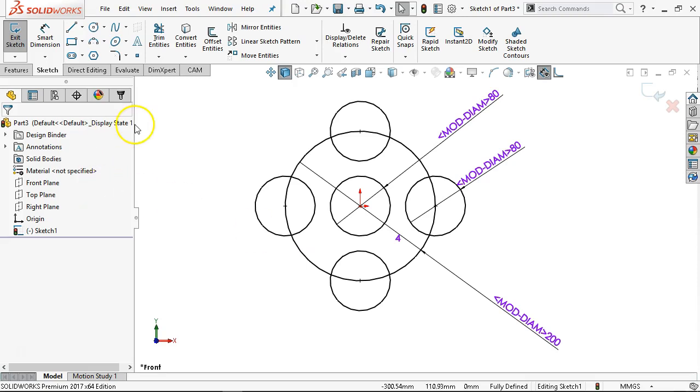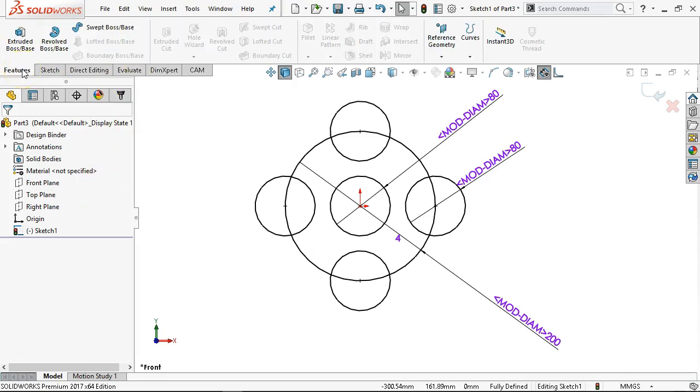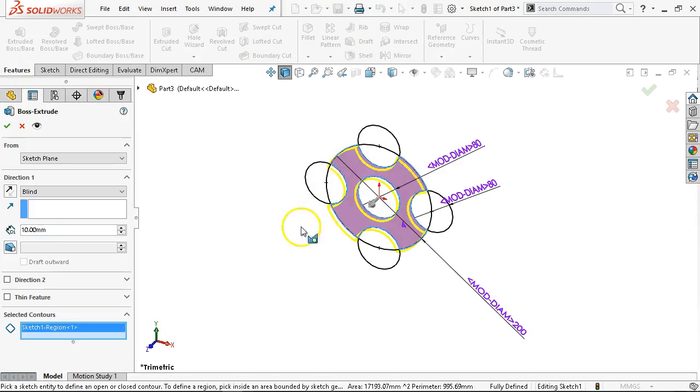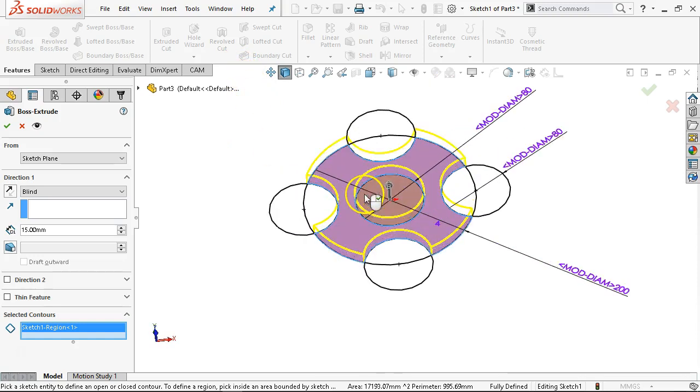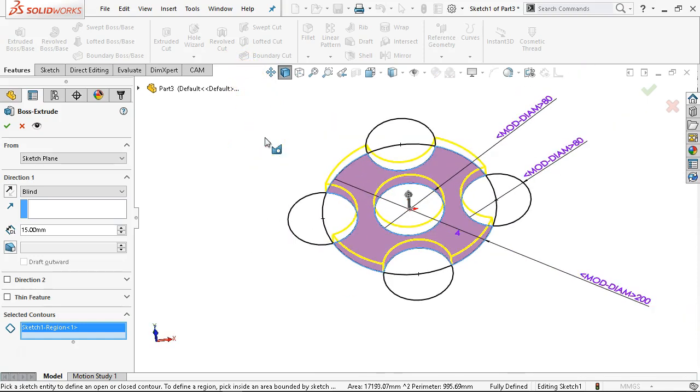All right, so at this point, if I'm happy with the contour and region, extrude boss base, there is my region, and this is 15 millimeters thick. And that is the result. And if I wanted to have some other component that was going to build off of these other tabs, whatever this locks into as a drive mechanism, maybe I wanted to build it separately or as another body, I can come back, share this sketch, and utilize those items.